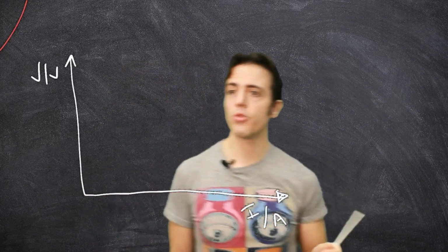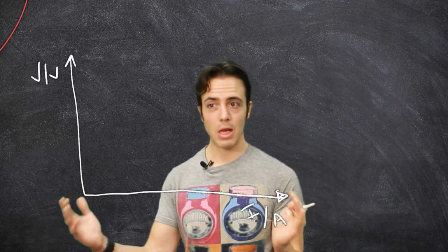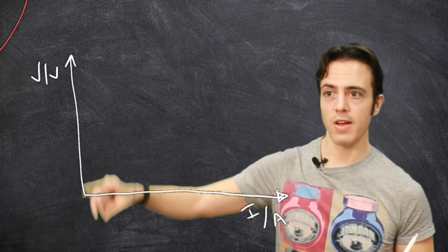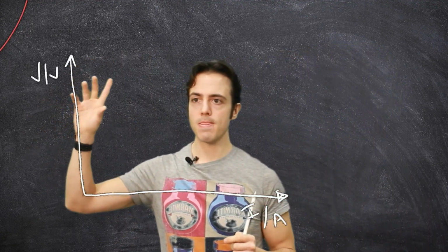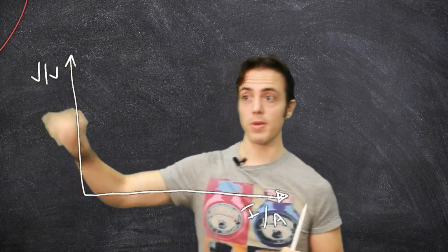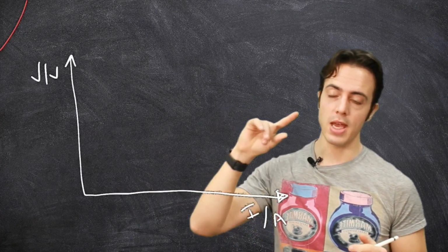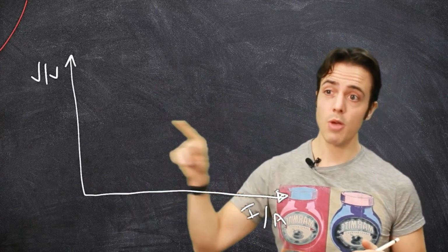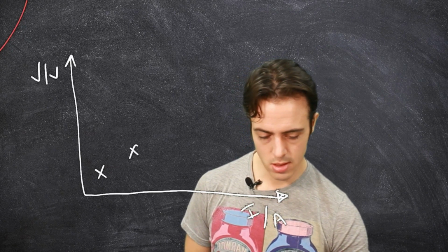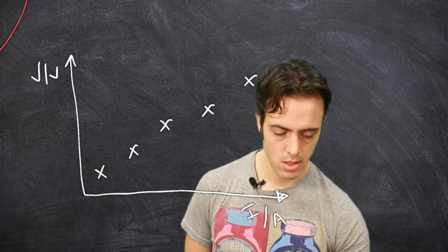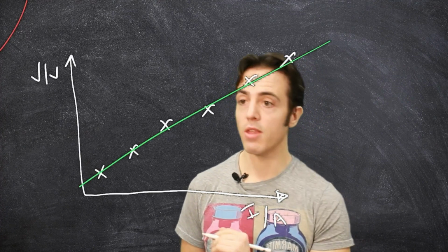We're often taught to put the independent variable on the bottom, that would be voltage, which will be varied, and the dependent variable on the ordinate, which for our purposes would be the current. But when we get the slope of the curve through here, if we do it this way around, the slope of the curve will be the resistance. So you guys are going to put your points on here, and then determine a line of best fit through them.